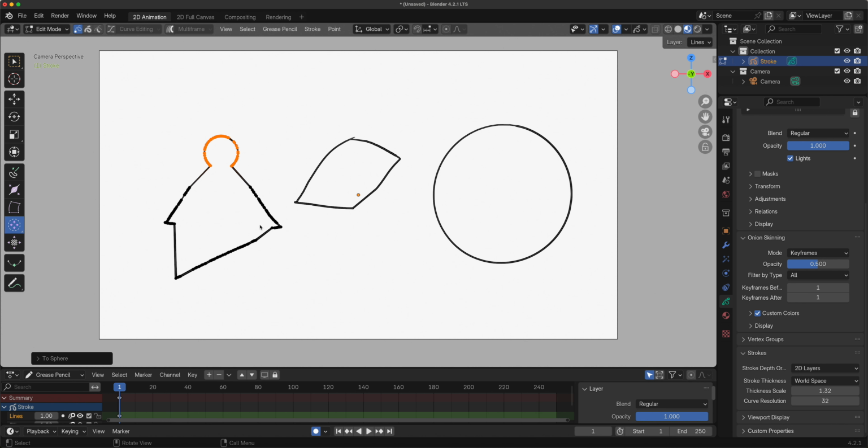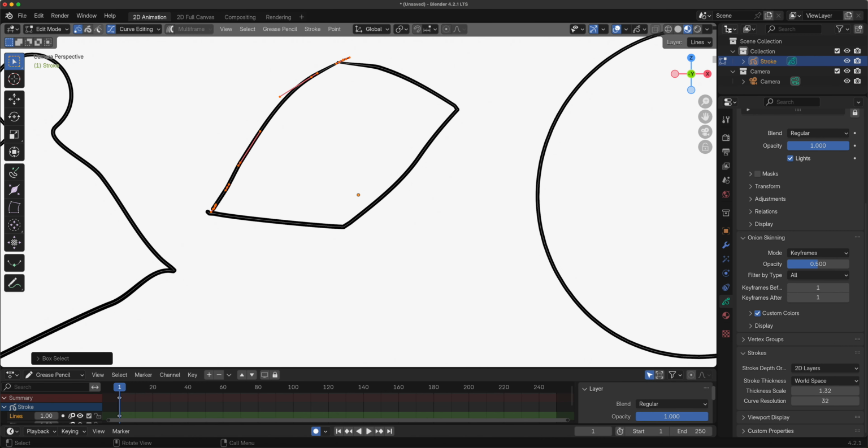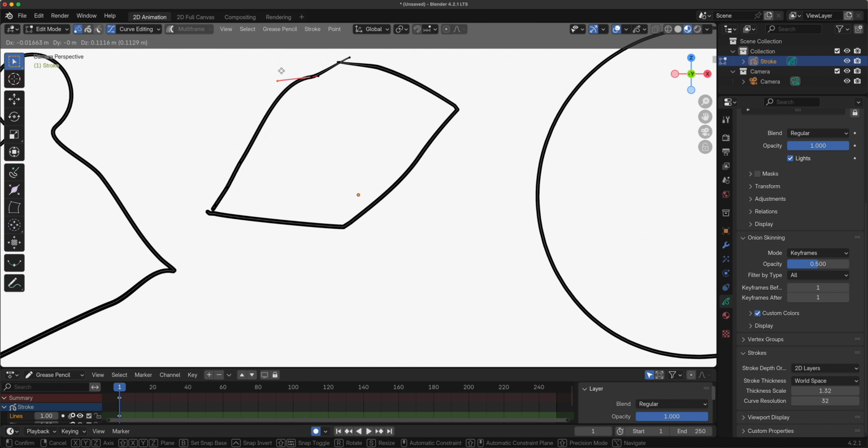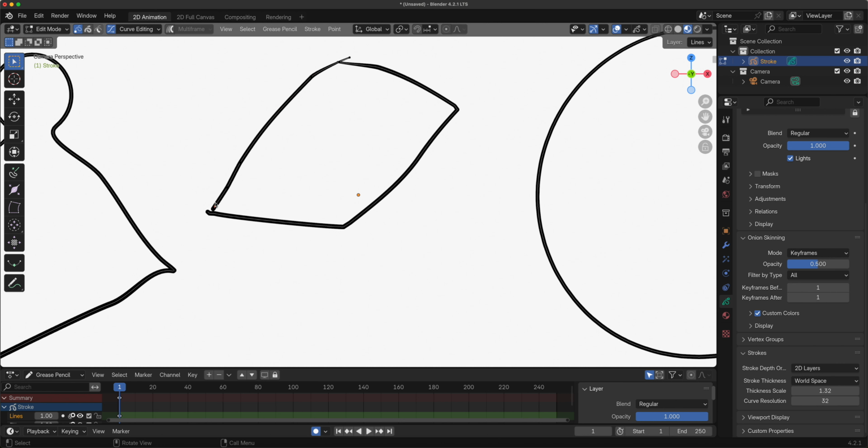Okay, and finally here we have curve editing. So with curve editing, any selection that you have, you've got to pre-select it first. So let's say we got a few points right here. Okay, if I zoom in, curve editing is on. You can select those, and then with a combination of the move tool, if I press G right here, then you've got your Bezier handles.